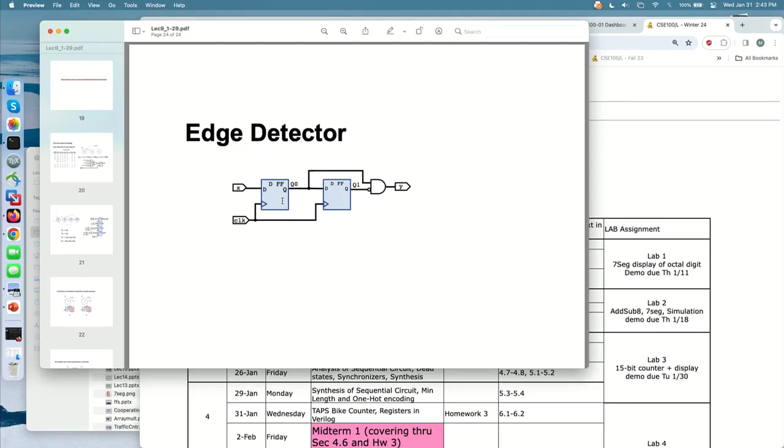And this first flip-flop actually serves the purpose of a synchronizer. So if you have a button feeding into this, you don't need to have a synchronizer in addition, because this is the only flip-flop that button connects to. If you do add another flip-flop in front of it, it won't hurt. It'll just delay it by another millisecond or so, or less. Okay.